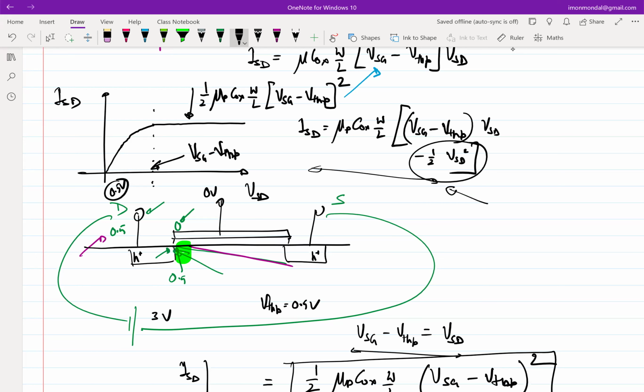So from a circuit designer's point of view, we are essentially trying to get into a zone where I don't have to think about what is happening inside the device. More and more we are trying to get into these IV characteristics, because we don't want to look into what is happening to the hole density, current density, and charge density inside.